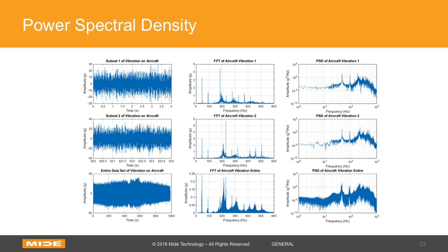But the PSD levels stay pretty similar the whole time. And that's a very important takeaway. The other benefit with PSDs is you can actually integrate the area under the curve to get RMS vibration levels. So PSDs are typically shown in test standards, and they are used to quantify your vibration environment and use that information to design your system. We'll get into that, though, in a couple slides when we talk about the response spectrum.